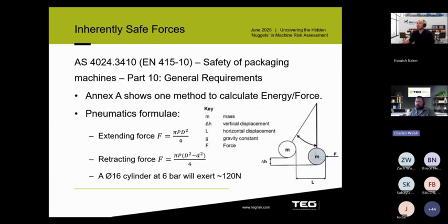And that's a good demonstration. If you can stick with those forces, that's an excellent demonstration of, well, we've done all the practical steps and we've gone with this because, well, here's a good example. When I went to one place that had pushers on their conveyors, we took off the covers at the back of the pusher, and it was absolutely disgusting. I was starting to dry retch. There was just gunk and crap everywhere. It was in a food processing facility, and they tried to guard this thing to make it safe. But in doing that, they had made a bug trap, and it could never be cleaned.